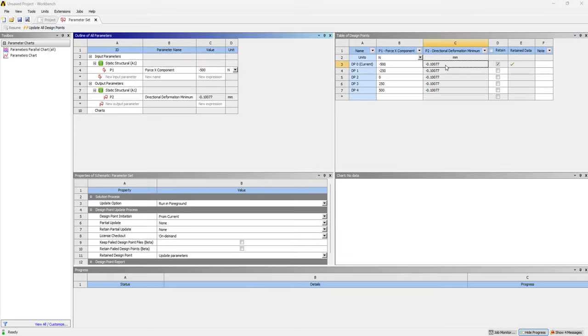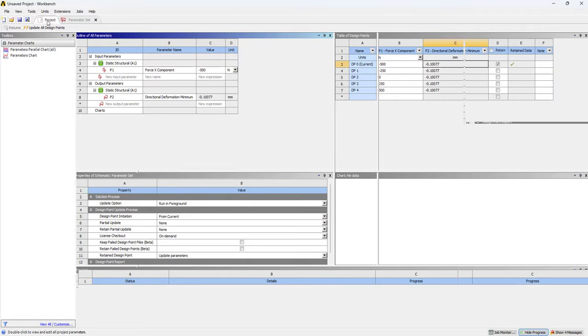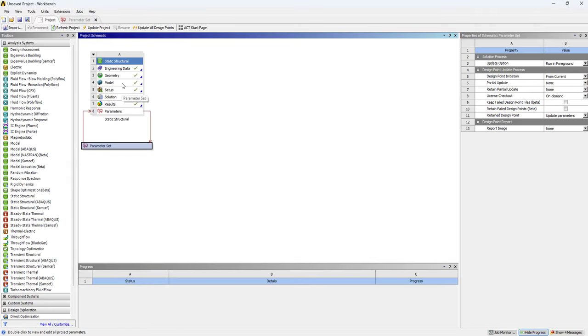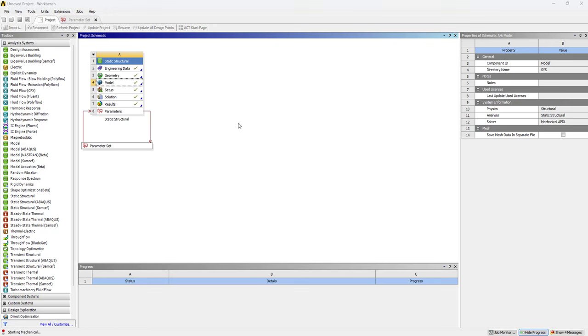The third iteration is also unsuccessful in reflecting the details of the stress stiffening, and the reason is that we are solving the problem as a linear problem, and we didn't change the analysis settings to capture the non-linear effects that can result from a large force in the longitudinal direction of the beam.